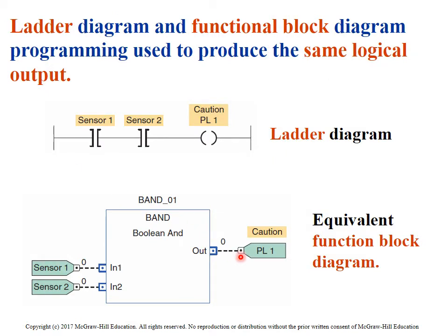So here's some of that function block diagram stuff I was telling you about. Typically you don't see a truckload of this out there, a little bit maybe. Essentially you're looking at ladder logic at the top and then a function block at the bottom. The same principles apply though. It's got N1 and N2 ANDed together for an output. Sensor 1 and sensor 2 have to be ANDed in order to turn on the output. Same principle applies.